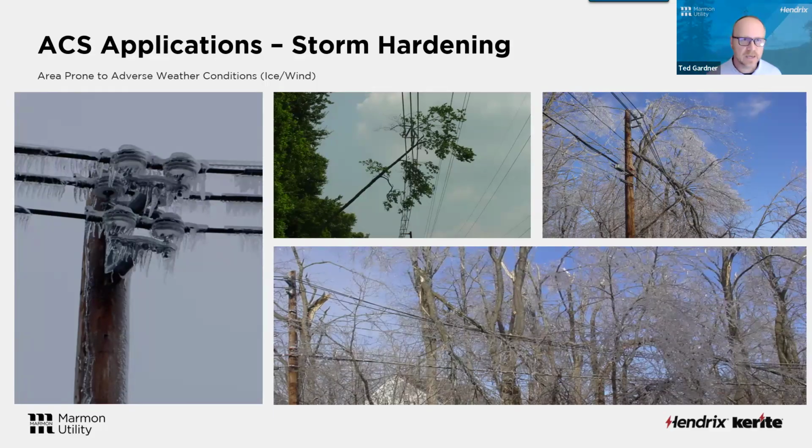We understand spacer cable is not something you're just going to start building everywhere and building everything out of spacer cable. You kind of got to pick your spots and find out where you can get the most benefit out of it. But like I said, we size everything by the NESC loading zones for your area. And we really focus on, again, sizing the messenger and the span lengths for that. Like I did say, you're going to have to increase the size of the poles, pole classes, most likely, but you can typically get by with shorter poles. So it's kind of a nice trade-off there. Typically, you can get a thicker pole a lot cheaper than you can get a taller pole.